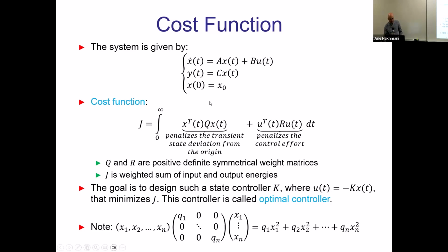So let's see what that thing means one by one. This part is easier. Think about a SISO system first, which means u is a scalar function of t, just some plot. So u transpose times R times u is just R u squared. So what is the integral from 0 to infinity of u squared? Signals and systems. Typically you also see that as the absolute value of u, because u might also be complex, but not in our case. It's like the integral of the absolute value of u squared dt. So you have a term for that.